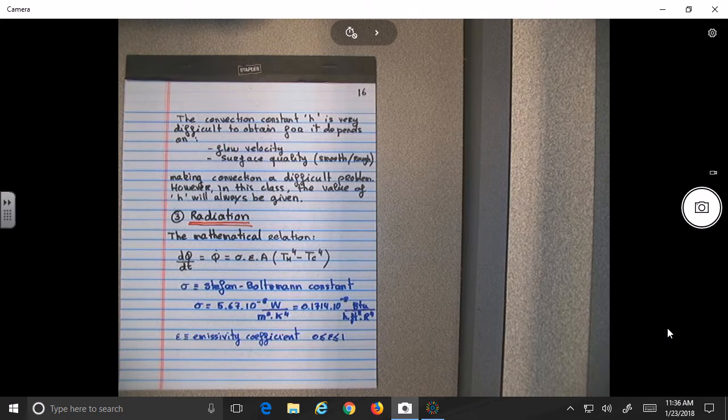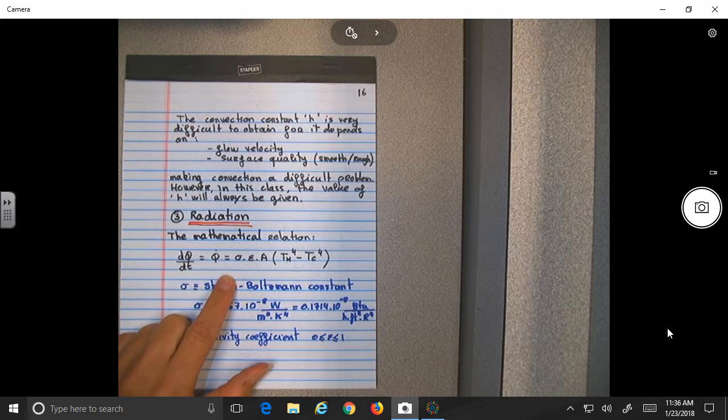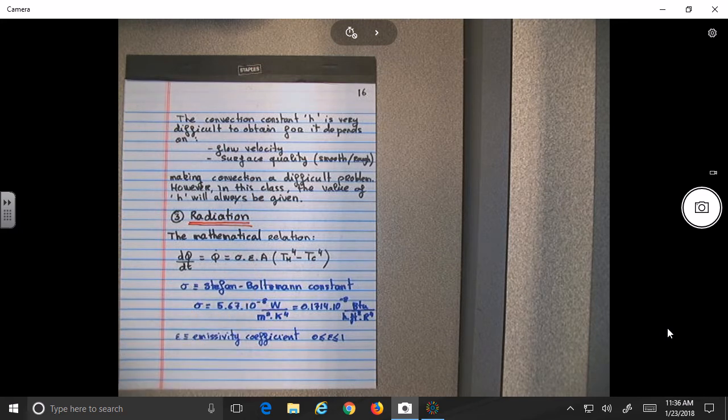So this could be called the absorptivity coefficient or the emissivity coefficient. The assumption when writing down this equation, and I'm not doing the derivation for you, is that an object will absorb heat the same way it will give heat away to the medium. So that constant, the emissivity, has to do with the material.